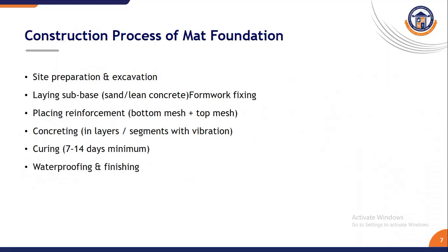Next, the construction process of mat foundation. The raft foundation is built step by step: excavation of soil to the required depth. After that, preparation of subbase with lean concrete or sand, followed by formwork fixing around the boundary, then reinforcement placement for the top and bottom mesh, and finally concreting in layers or panels using a vibrator to remove air voids.